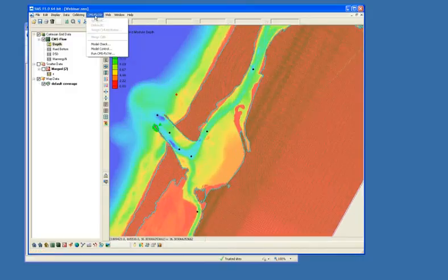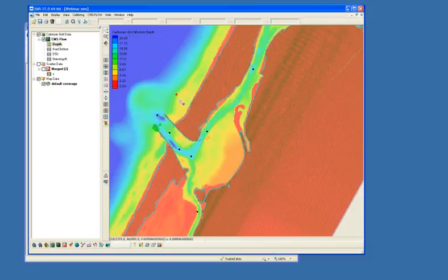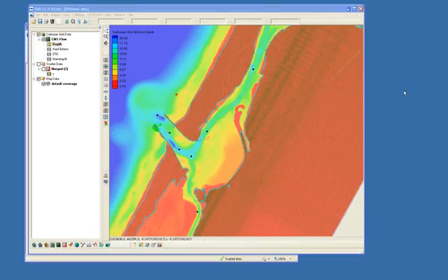So you would fix those, try to run again. If it still didn't work, maybe lower your time step a little bit and see if it got a little bit farther. If it did, then normally that would be a current limitation. There's some other things that you could look at as well, but those are the major ones. Hopefully that answered your question for right now.